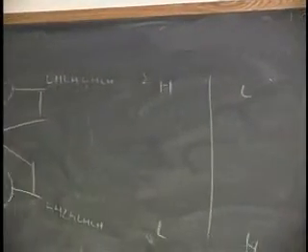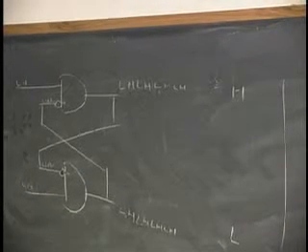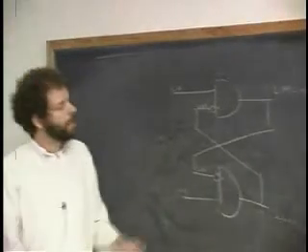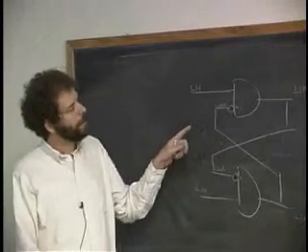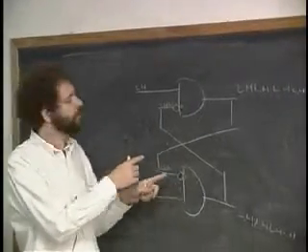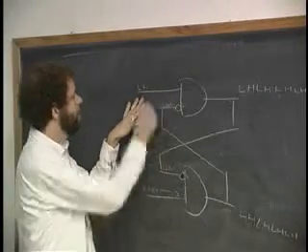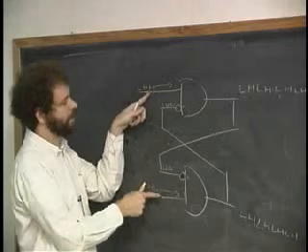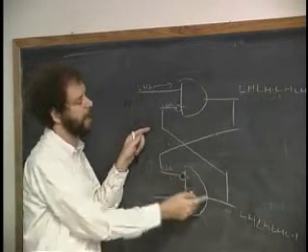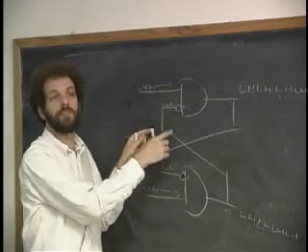Why would that ever happen in a circuit like this? The electricity going around in one path may be a little bit slower than in the other. It may be the case that the time delays in the circuit are not exactly the same. Think about this: if both of these are high, and staying high for the rest of time after we press the button here, both at the same time, it may be that the high values as they propagate around are a little bit slower or faster than the lows.